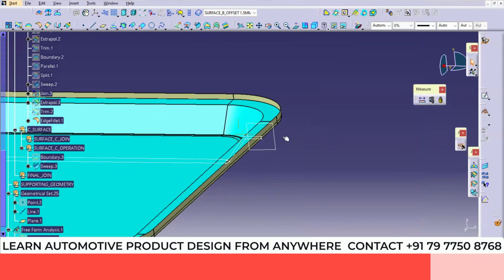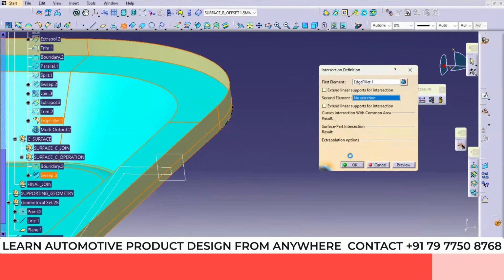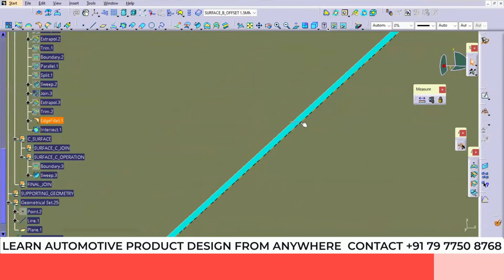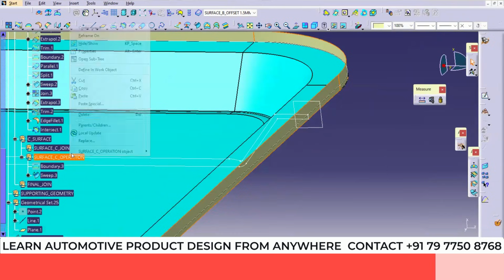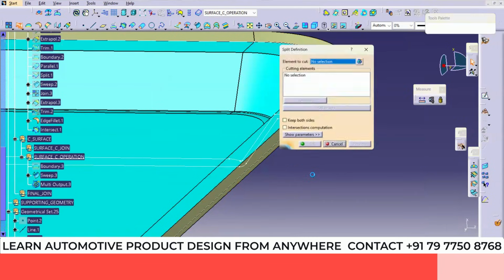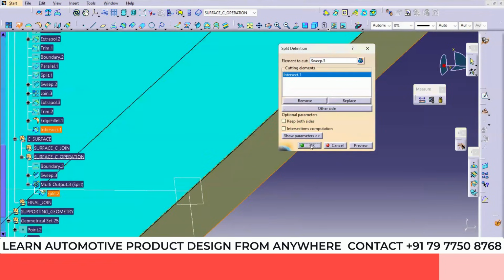Right. Or first I'll check an intersection. Intersection of B and C. So we are getting one intersection line because B surface is a little extra here. So I'm going to cut that. Okay. So in the C surface operations, first we'll split the C surface. Okay.